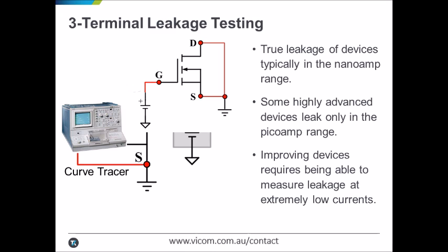If manufacturers wish to keep improving the leakage performance of their device, being able to measure current in these low ranges is required. Fortunately, modern instruments like the source measure unit have the capability to characterize typical leakage current even at kilovolt levels. We'll go into the details of a source measure unit, or SMU, shortly. Measuring gate leakage is one test that is very difficult to do on a traditional curve tracer, but is very easy to do with SMUs.